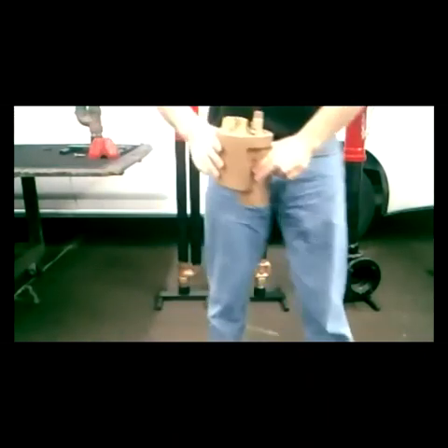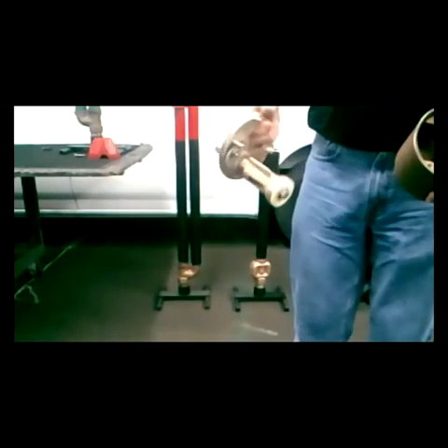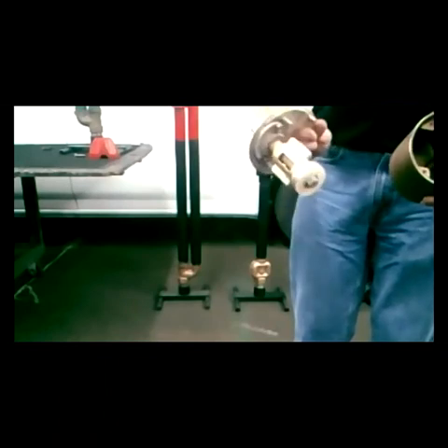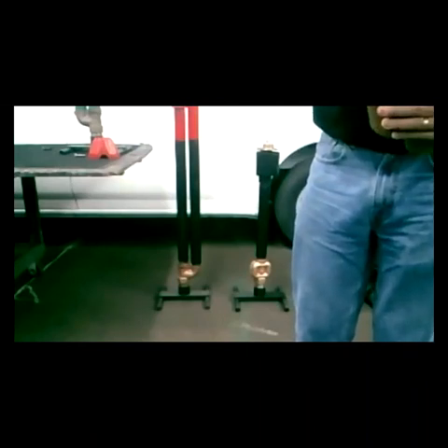And that's this one here. So this just goes onto a 2-inch connection. It's for warm climates, not freezing. And again, the guts, it's just, again, a plunger design, but a short plunger with the seat. So the only maintenance I do on this is I replace the seat, put it back in, turn on the water, and again, away we go.